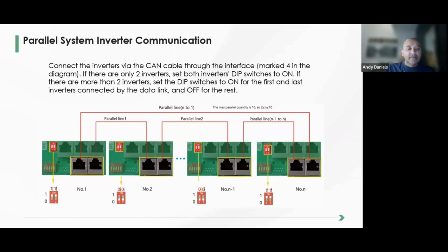Number two, have a look inside these RJ45 plug ports. Shine a light inside there to make sure that there are no critters or dirt inside. We've had guys working quite rapidly, crimping cables, cutting insulation, and something drops inside there, and then they don't get proper communication. So if you're not getting a complete closed loop, just unplug them, have a look, and also do some cable testing and recrimp the cables. Once you've set the dip switches and you've done the closed loop, it works like a charm, and it works for a long time, all the time.